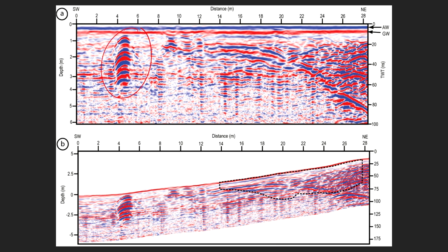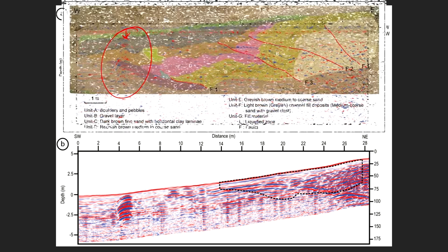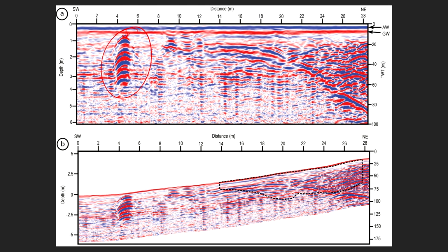This is the reflection of the pipe here, and it was not very deep, it was kept shallow. So we avoided this area and dug the trench only in this portion, which is marked here after the topographic corrections.